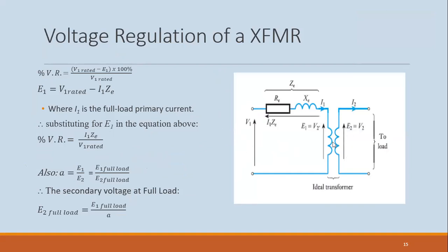Now, to make sure that we have 400 volts out here, when it's fully loaded, we would actually have to raise the value of E1, right? By a few percentage. So let us see, 400 minus 377.